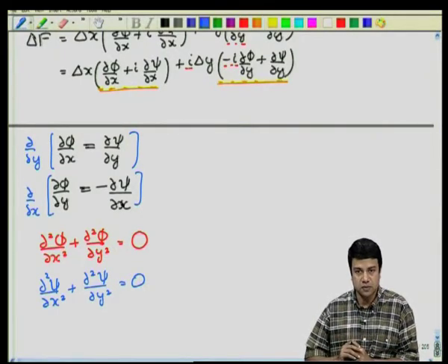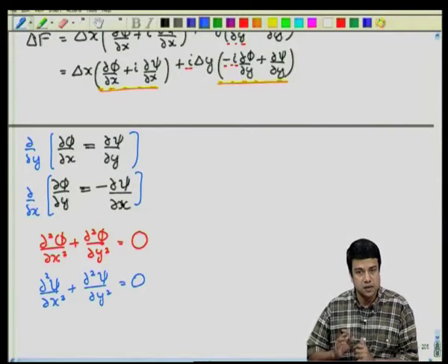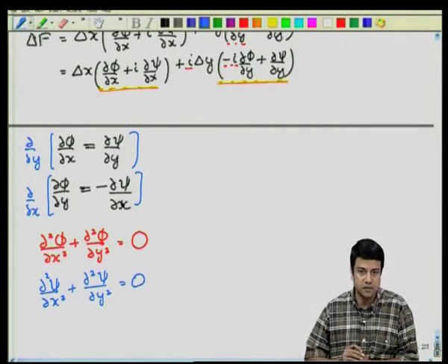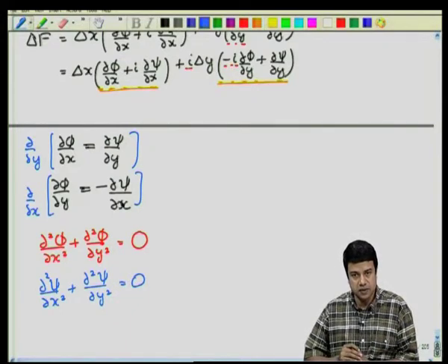As I have already shown you, solutions for potential flow are unique. Therefore, you can have only one solution which satisfies the boundary conditions and is an analytic function in the complex plane, and therefore, it satisfies the potential flow equations. So, for this analytic function, since I know that the real part satisfies the Laplace equation, without loss of generality, I can assign phi, the real part, as the velocity potential.